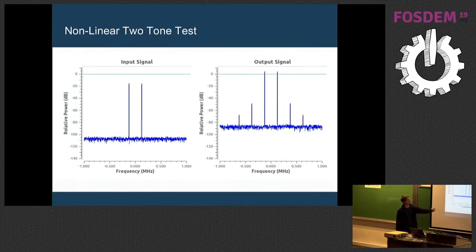So if we put this into GNU Radio, this is now our input signal. We have basically the same output power on the fundamental. We will get a little bit of extra contribution, and we're seeing the third order plus a little of the fifth, and the fifth order. I didn't include a seventh, so it's just not there. But I'll quickly swap over, and we can run this live.